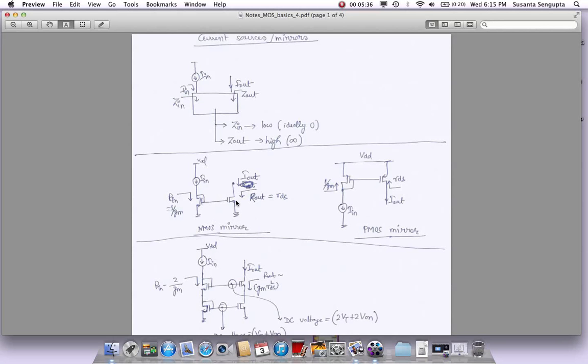And why do we do this? As I said, this is a current coming from some other circuitry on the chip, a biasing circuitry giving a current. You might have 5 different blocks that you want to provide bias current. Well, you cannot tell the biasing circuitry to give you 5 different currents. It can give you one, and then you build this current mirror. So here we are taking the input current and providing the bias current to some block.